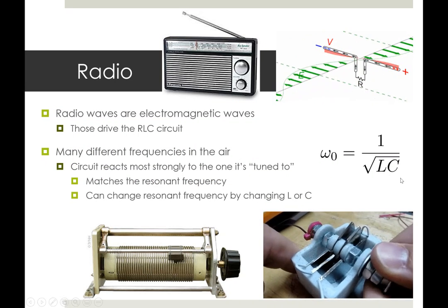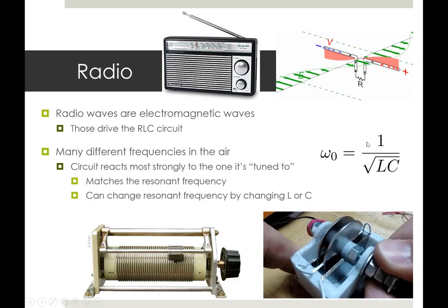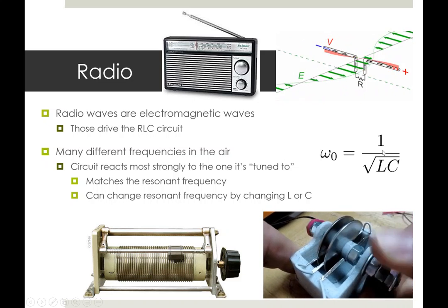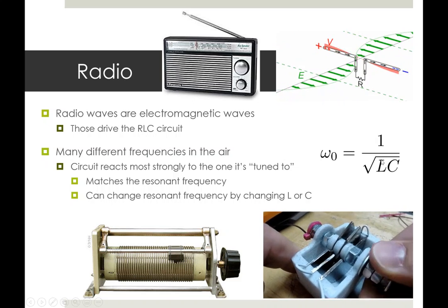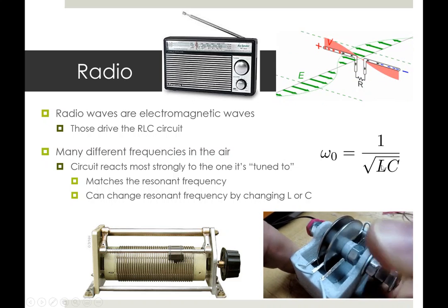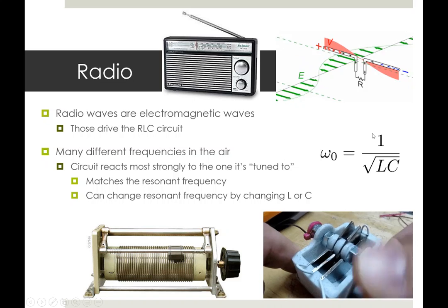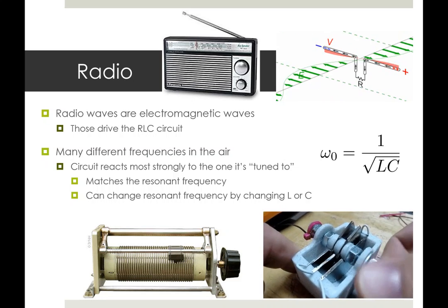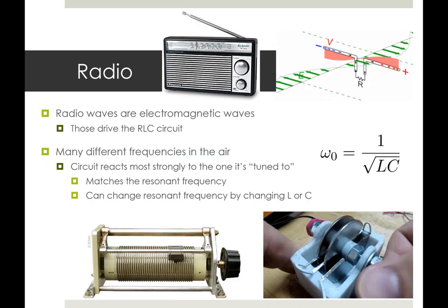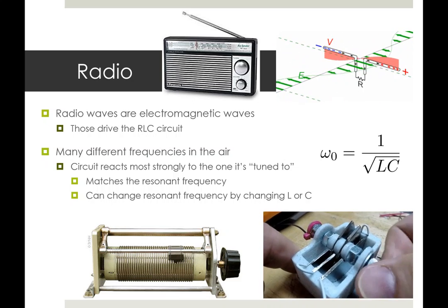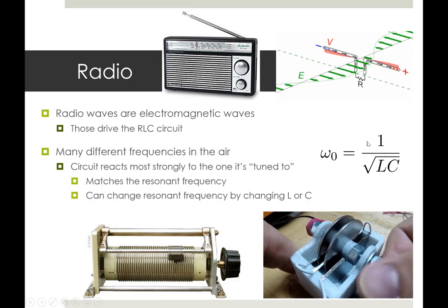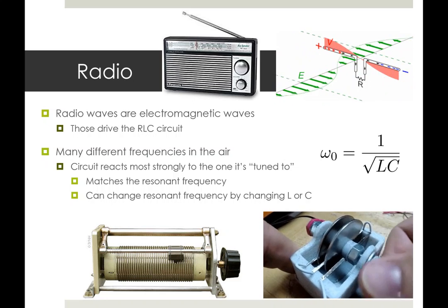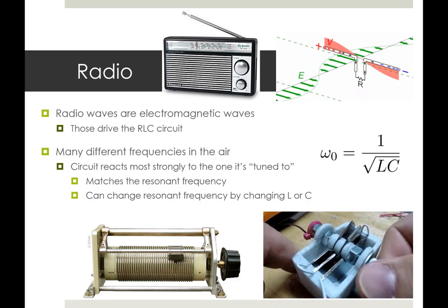And choosing that is very careful, that you need to choose the inductance and capacitance to be at the right resonant frequency to match the radio station's resonant frequency, the frequency that the radio station is trying to put out, but also choosing your inductance and your capacitance and your resistance very carefully to have the right quality factor, neither too big nor too small. And it turns out that means, in designing your circuit, you want to then have flexible control over the resistance, the inductance, and the capacitance.